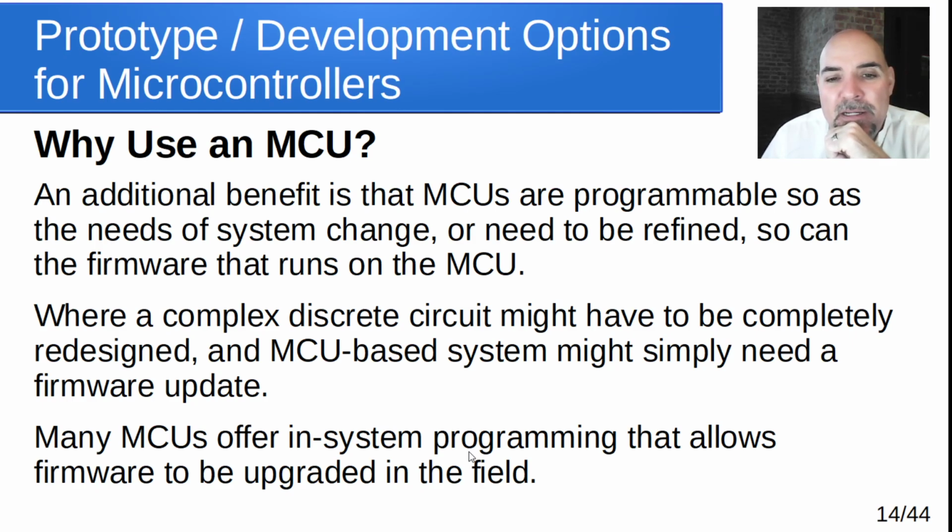But it could be that you just update the programming, and a lot of microcontrollers offer what's called ISP capability, or in-system programming, which means that you can take a program and update it, like updating the firmware of your product in the field. So in other words, you could push out those updates to products that somebody's already bought, so they could have the latest and greatest or the bug fixes or whatever, without having to bring it back in and reprogram it and send it back out again. You could do it in the field.